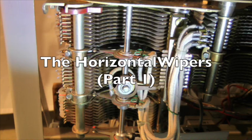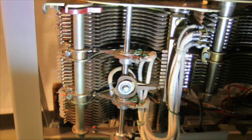The purpose of the bank assembly is to provide a convenient area for a line finder to achieve connectivity to any of the 200 line circuits terminating on the bank. This is accomplished by means of these 3 wiper assemblies. The lowest wiper assembly can connect to all 100 tip and ring terminals for line circuits 00 to 99, which are on the lower bank tier.